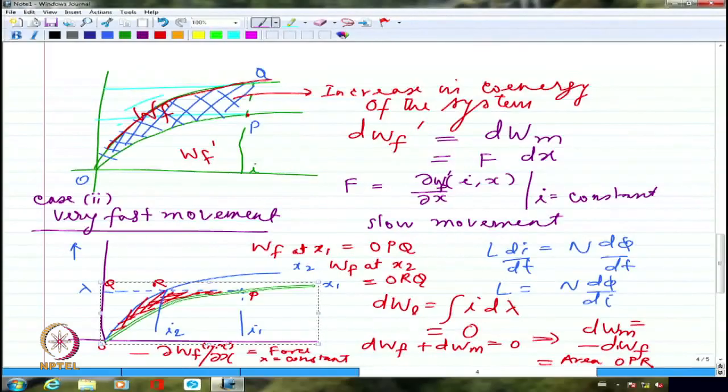It is very much fine. Why should it increase? Lambda multiplied by the reluctance. Reluctance has decreased. Lambda has remained the same. So lambda multiplied by reluctance is MMF. MMF has decreased. In the first case, MMF has remained probably the same, whatever, but here the MMF very clearly has decreased. Right?